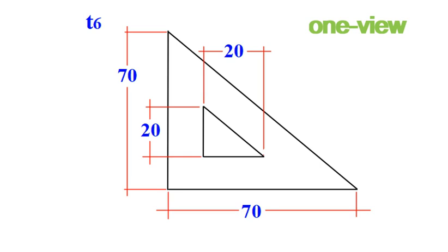First, for flat parts with a constant thickness. Imagine a simple metal bracket or a gasket. Instead of drawing a front and a side view, you just draw the one view that shows its unique shape. Then, you simply add a note like thickness 6 mm right next to it. Boom. Done. The note tells the machinist everything they need to know about that missing dimension.